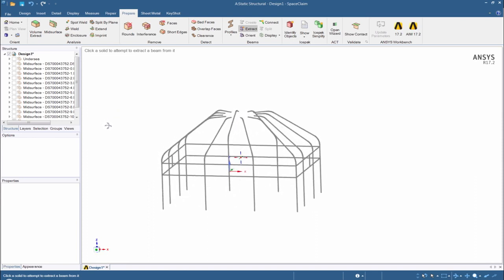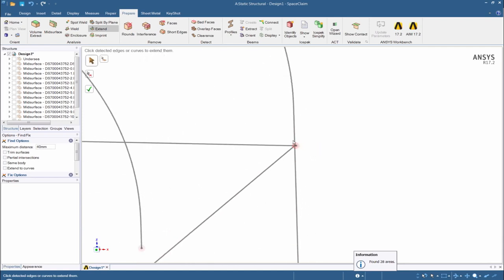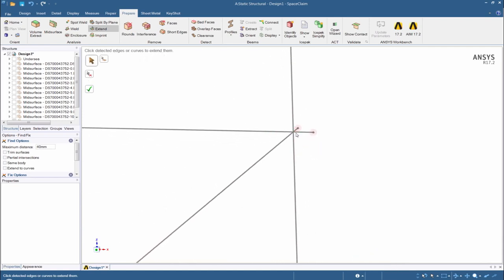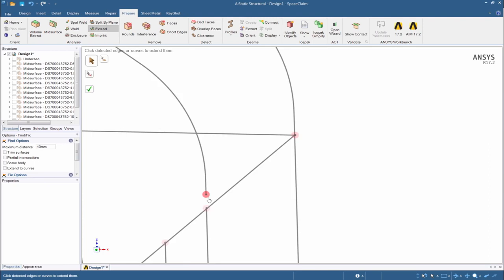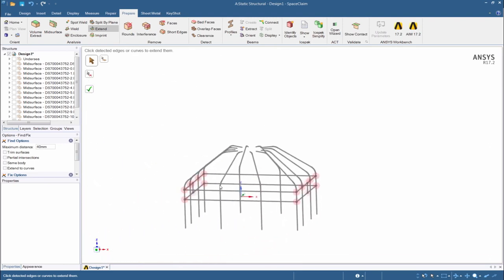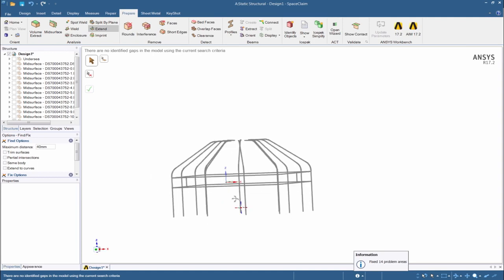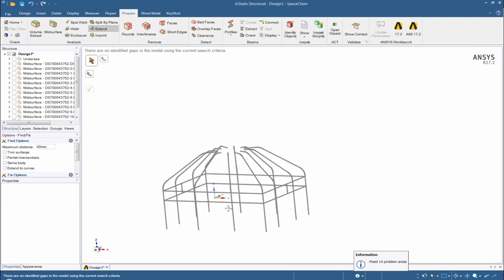And it does. Now, I know we started with kind of dirty CAD geometry, so I want to run this extend tool that's going to go look for anywhere where maybe things didn't close up properly, or maybe there was some overages like this, for example. That's not good, or these gaps that were left. SpaceClaim's great at finding those and just eliminating them for you and letting you know, hey, this was a problem I think you should fix, and we do. So we're in good shape now.